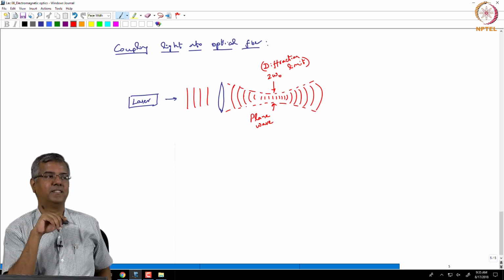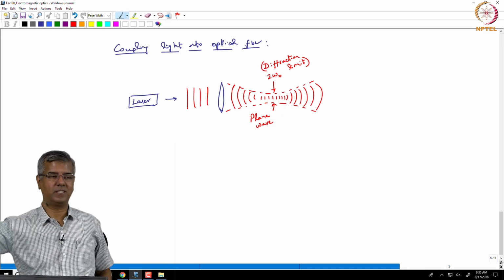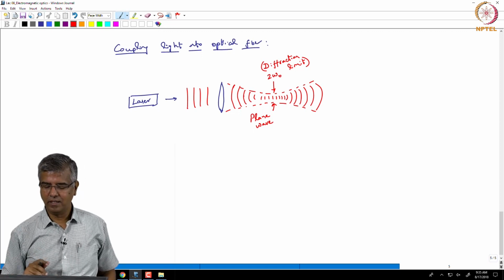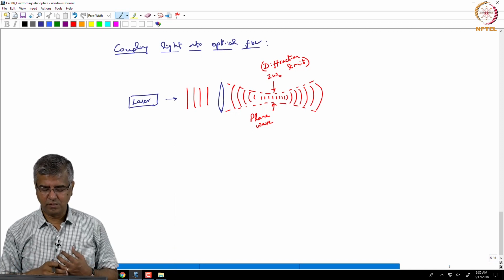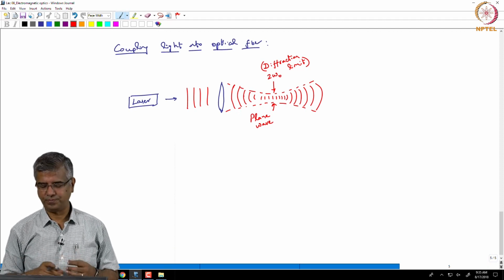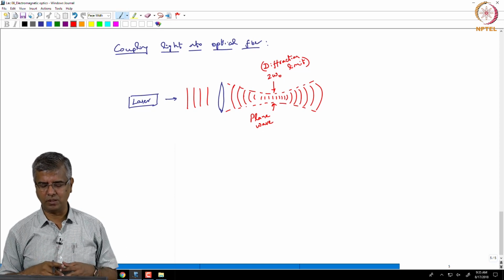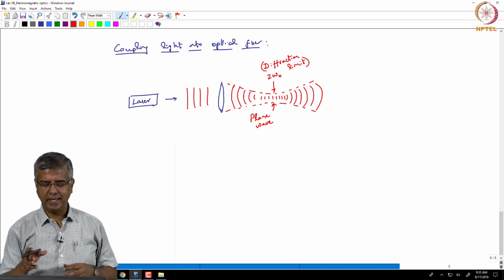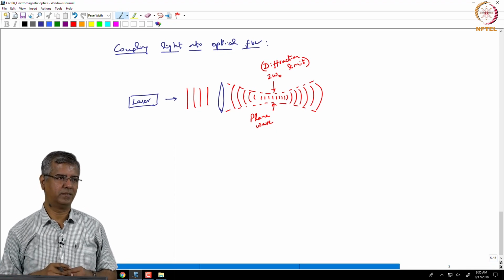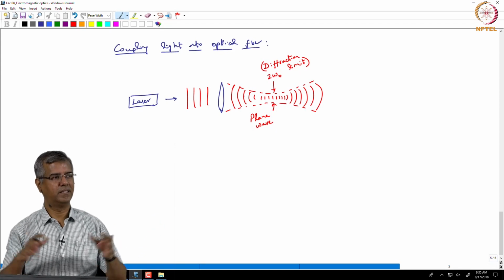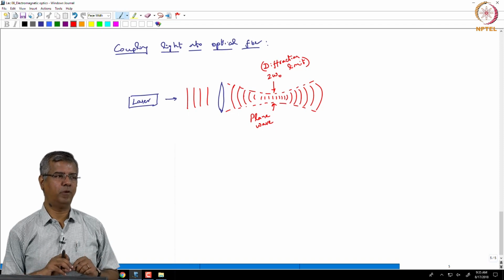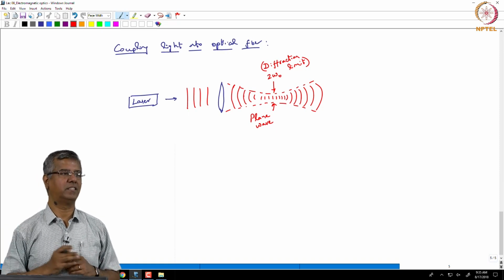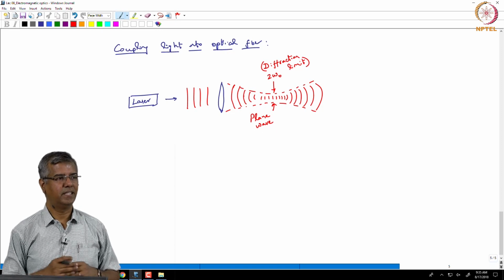So what you have in a single mode waveguide is actually a plane wave front that's moving all the way across. So that's an interesting thought, because when you look at any of these optics, when you're trying to focus light to a spot, it gets to a plane wavefront only at that spot, and then beyond that it starts showing this curved behavior. If you want to capture that plane wavefront and transmit it over a long distance, this optical fiber is a very nice way of doing that.